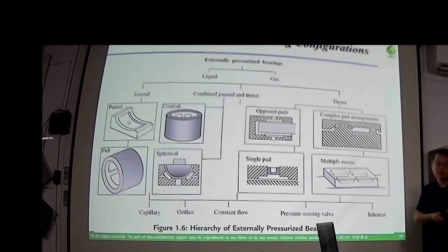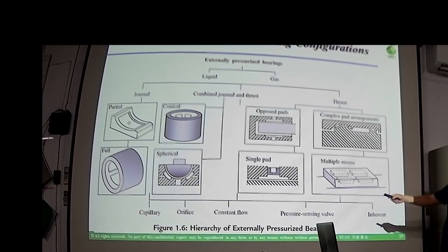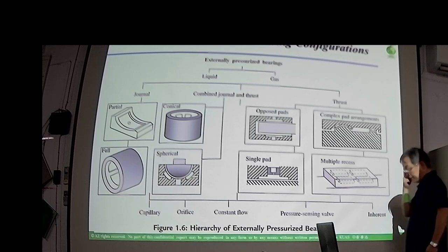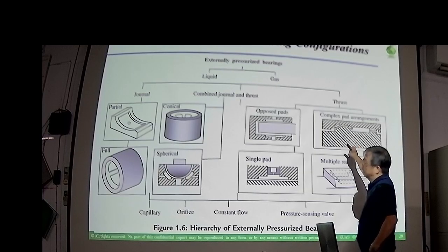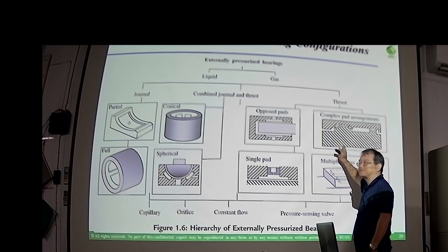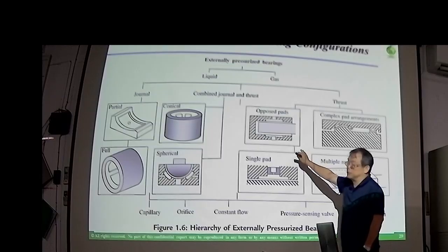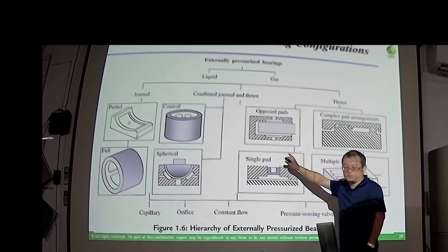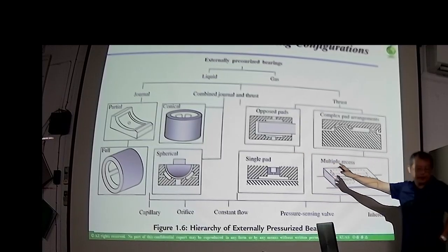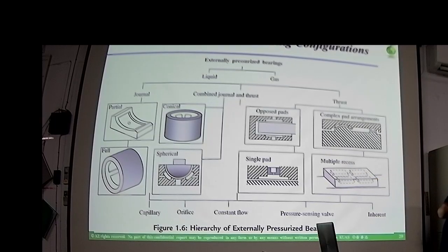For the milling machine and the turning machine, the cutting force is 10 times and 100 times bigger than the grinding machine. Therefore, you need to have a closed form slide table or closed form thrust bearing in this case.